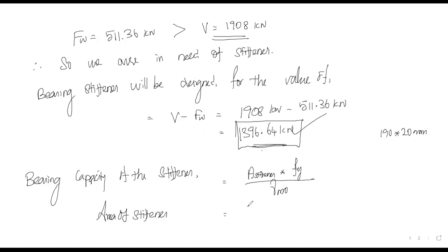Here I have the coping of 15 mm, and then the stiffener plate. I have to deduct this coping from the stiffener length, that is 190 mm I am going to provide.